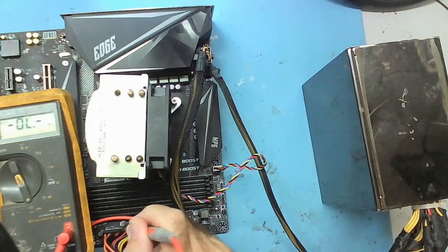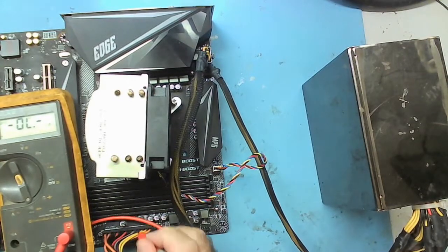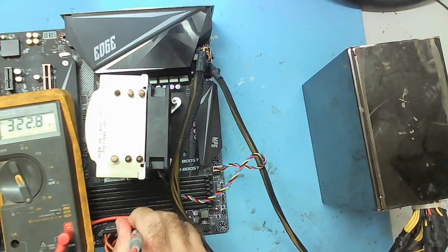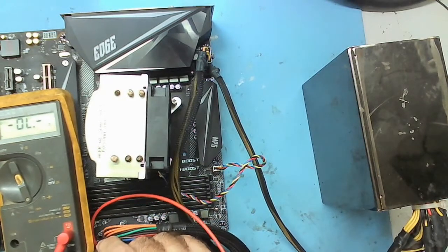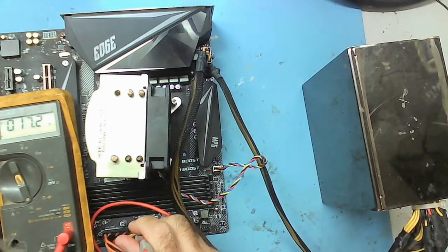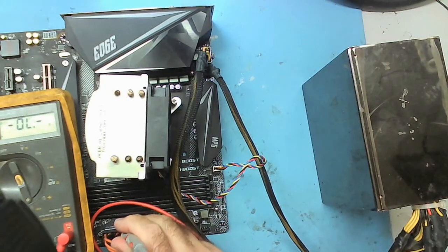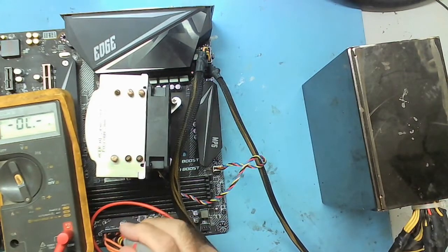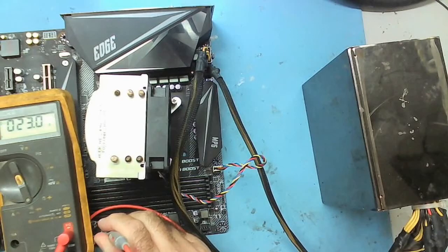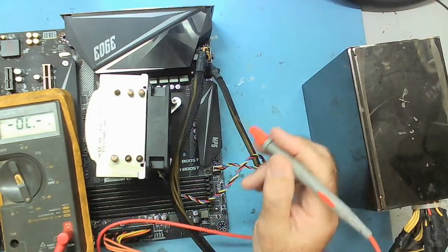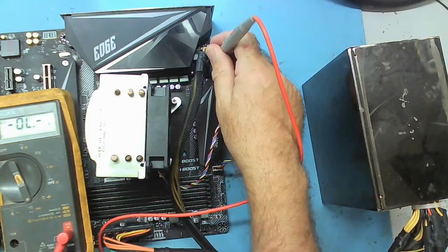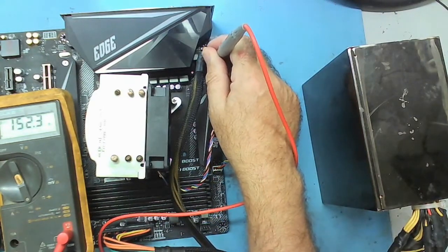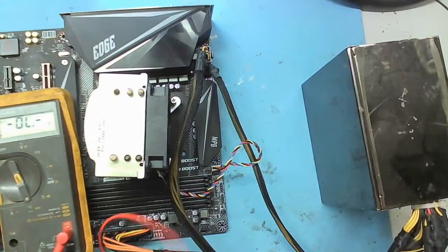Where's standby? I think the standby's a purple one. Yeah, nothing on that one. Or is it the green? I think it's the purple standby. No shorts there. This is probably the 5 volts, so I'm guessing this is the 3.3 volts. Yeah, I don't call that a short. I mean, come on, we've had GPUs at 0.6 of an ohm and they're not short. If you couldn't see the meter before, that's off the 12 volt connections. Okay, no shorts.